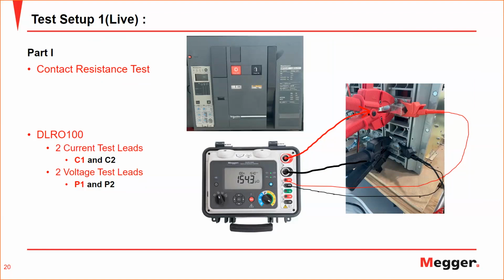But I deliberately make the current cables a little bit far away from the voltage cables. They are not connected exactly at the same point, but the breaker I have here with me in the office is quite small, so there is not much space to create a huge difference between them. So maybe the picture is not showing it very clearly, but there is some difference between the voltage and the current cables.